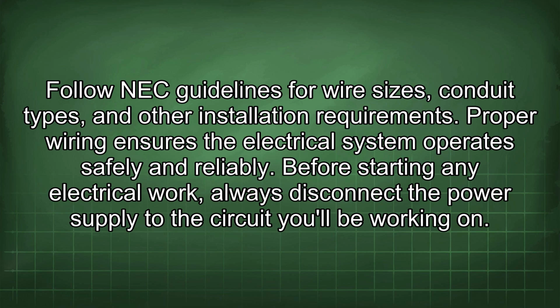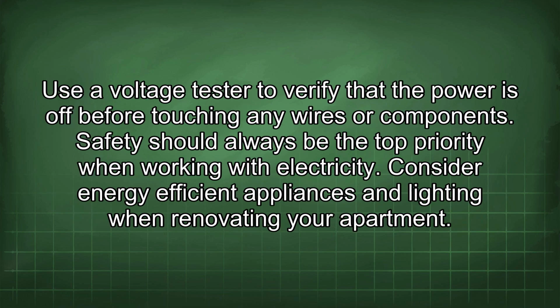Before starting any electrical work, always disconnect the power supply to the circuit you'll be working on. Use a voltage tester to verify that the power is off before touching any wires or components. Safety should always be the top priority when working with electricity.